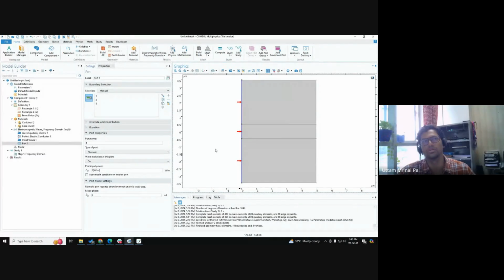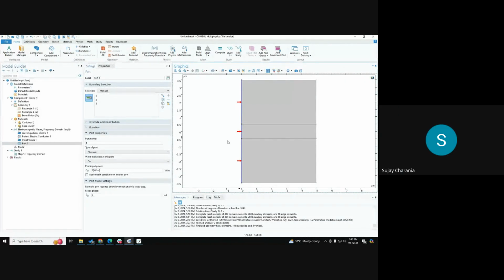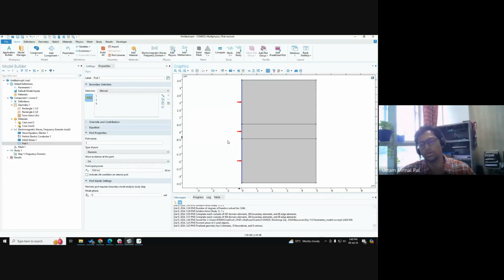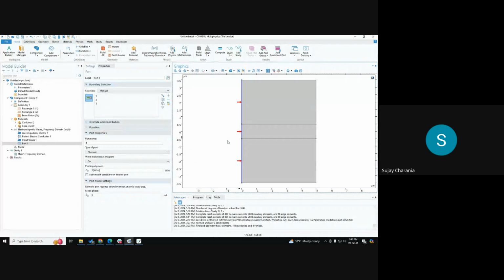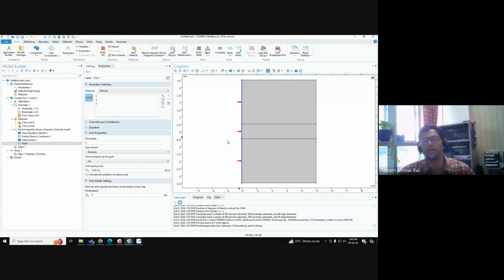So based on the numerical aperture, you're trying to only excite the core. Even if you excite the core, depending on the refractive index difference, it will either give an evanescent field or you won't have these fields. Particularly when we do experiments or a theoretical study, we only apply the field to the core, and then we automatically see that field go towards the clad. Over here also you will see that happen.